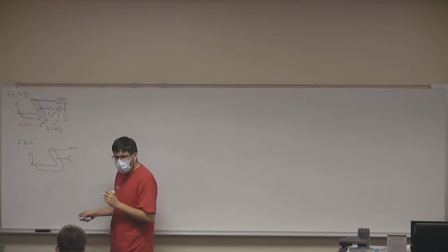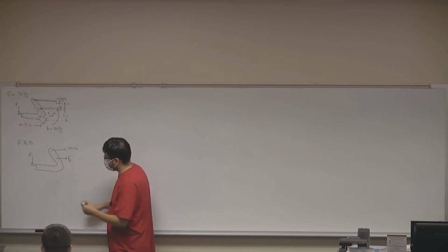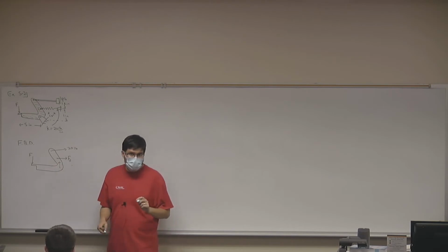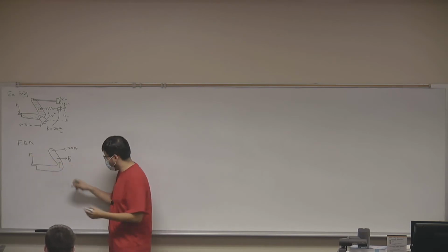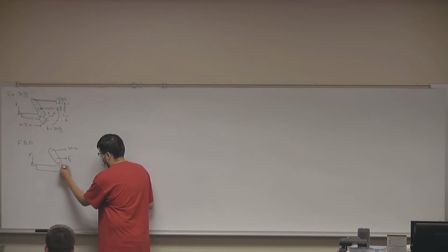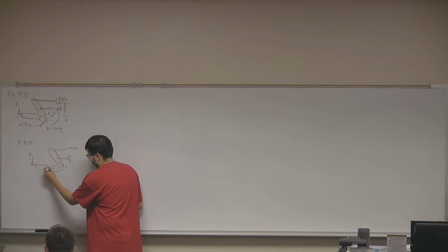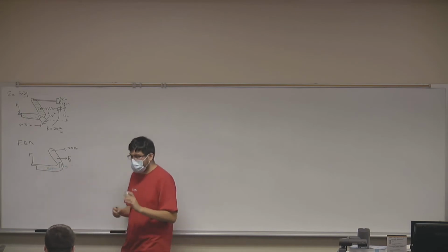I'd like to say that it's safe to assume that the Y reaction force from the hinge is in the upwards direction. Do you agree? Okay, it's safe to assume that my Y reaction force will be up. And I'm going to assume that my X reaction force will be towards the left. Can we agree on that? Okay, good.